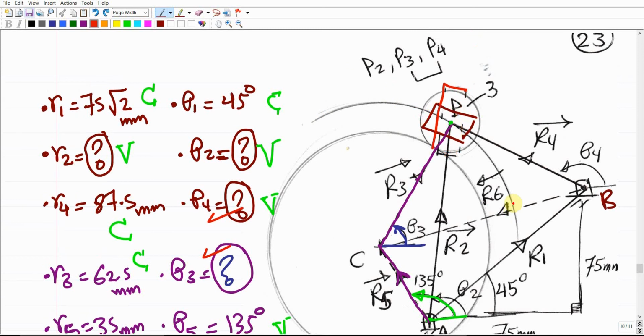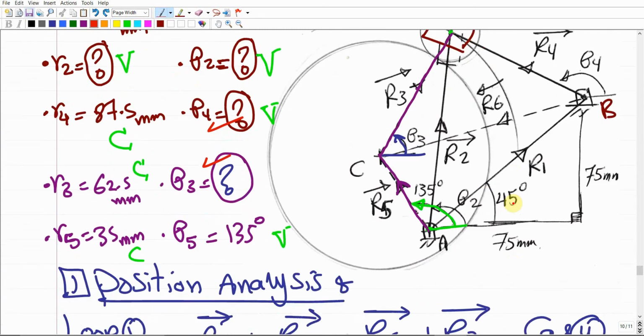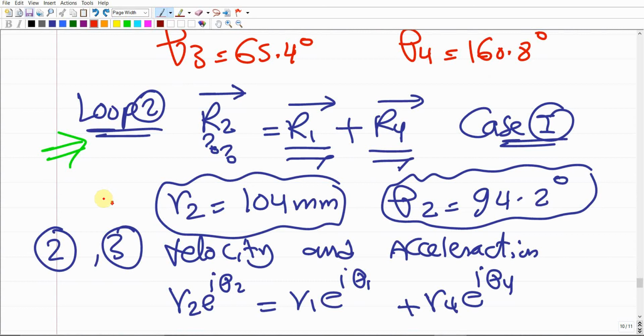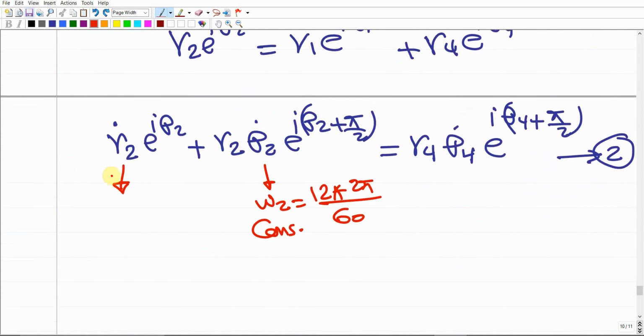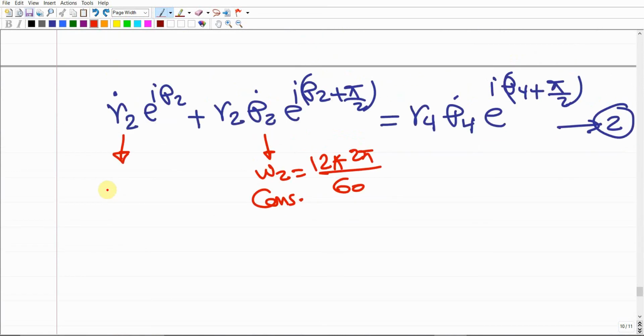But we're gonna go through these details. For this one, simply we do have R2 dot, which is shortly related. We said that R2 means V. It means that this is the sliding velocity related to the virtual slider that replaces the roller itself. Definitely this R dot will be unknown. Theta dot, which should be omega 4, is also unknown.